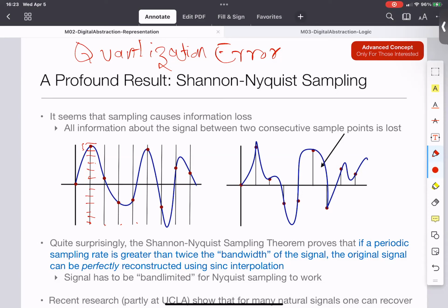On the other hand, for something like temperature in a thermostat at your home, you can probably get away with 8 bits or something like that, right? We don't need to be super accurate, and the dynamic range isn't a whole lot. Temperature at home, from maybe a little below freezing, to say, -50 Fahrenheit to 120 Fahrenheit, something like that.